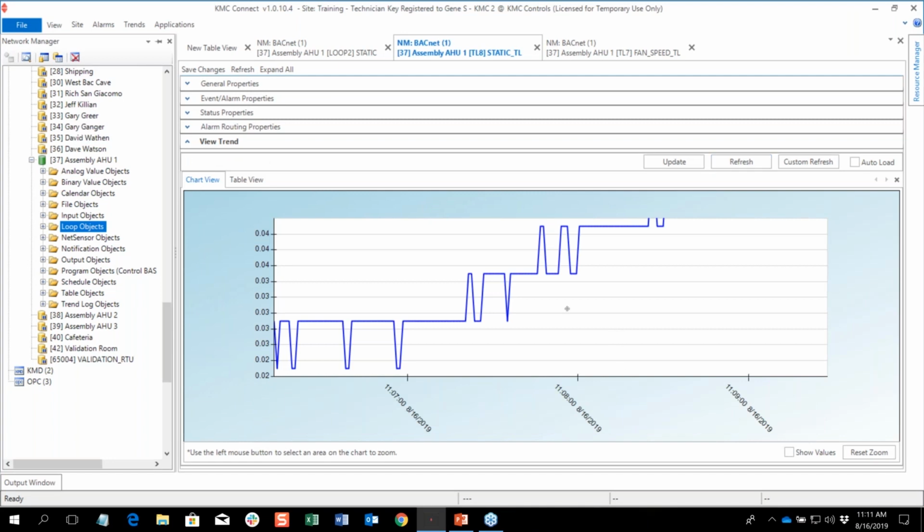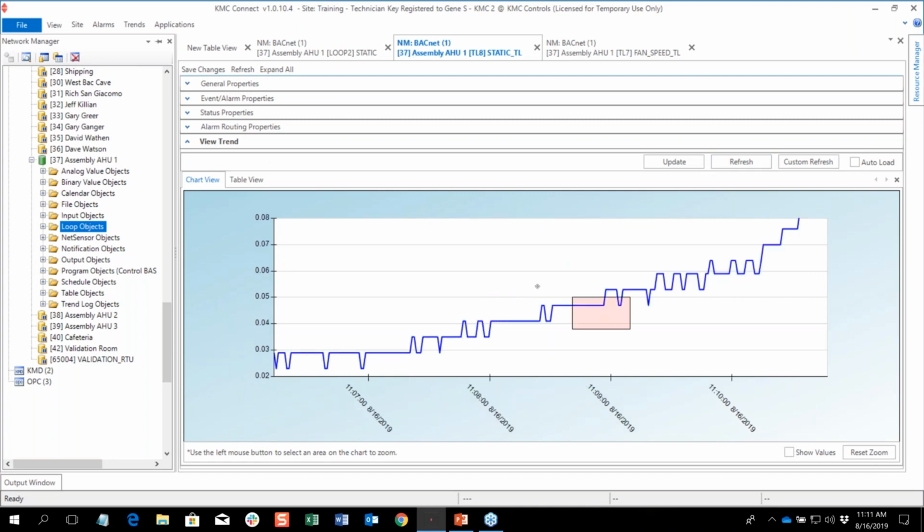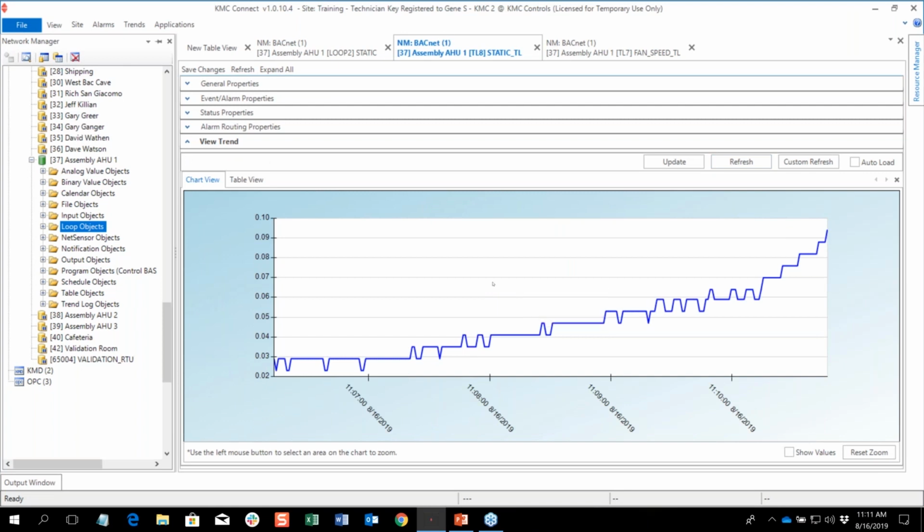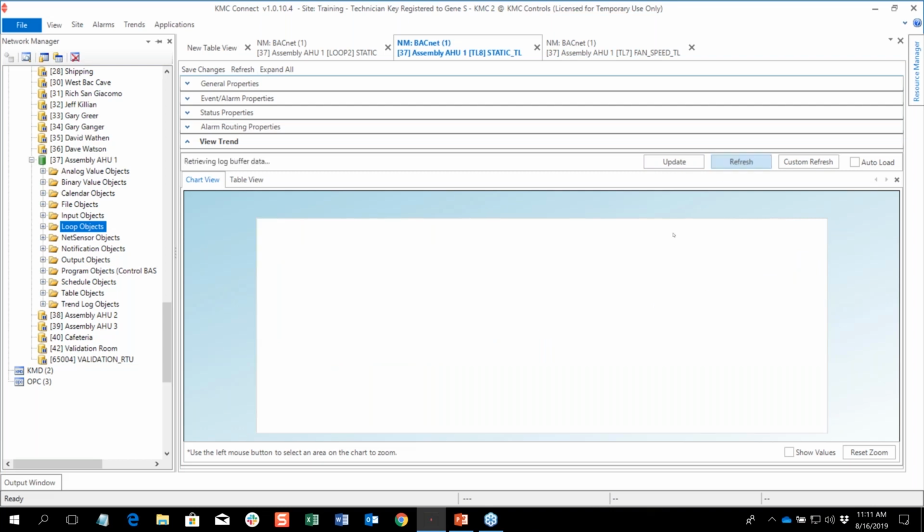But again, that math is in the presentation. It will work just the same for other loop values, mixed air loops, DAT loops, but we may be starting with a different number of cycles per hour we want to attain and a different proportional band. But yeah, reference back to the math, and again, if you have the proportional term that creates something stable, we know what proportional term to plug into that math as a starting point for that integral constant.